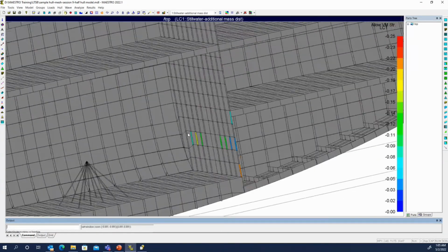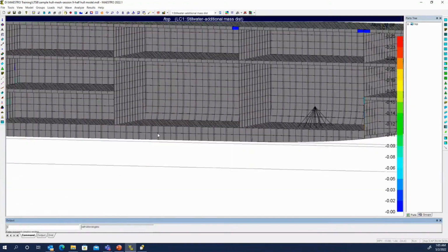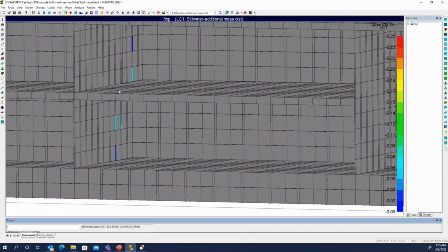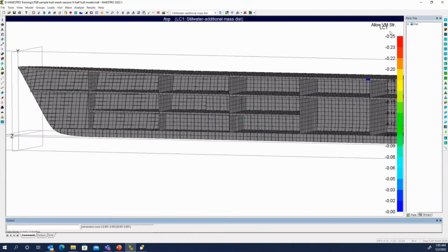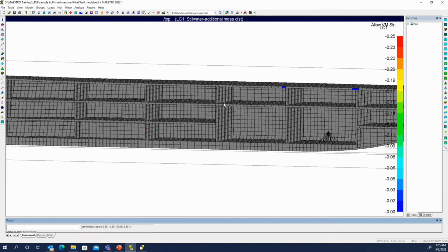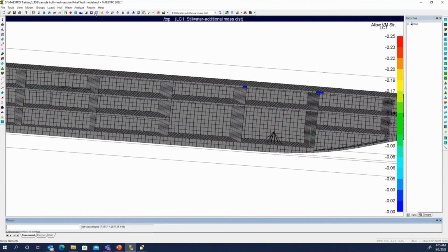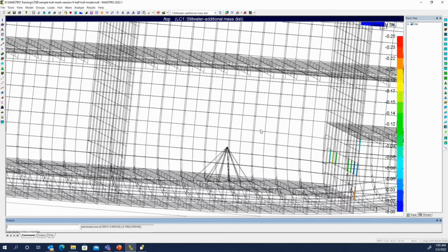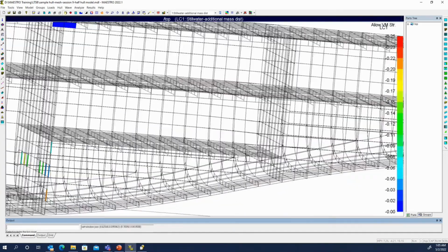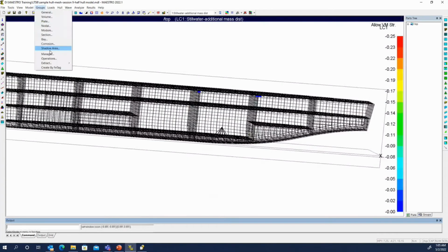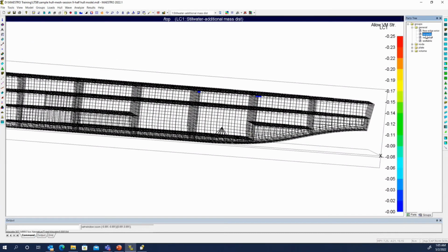If we zoom in a little tighter, we can see, oh, I've got some beams there. Other tall ones, I'm not seeing much. There's a few more, but nothing that was in red indicating the 0.25. If we hide outside the range, it's still difficult to see where that is. Where using that group extract can be very helpful. We say only the negative values, and we already had a negative adequacy group there, so now I create a new one with a pound sign on it.